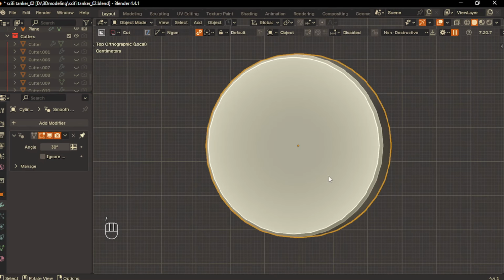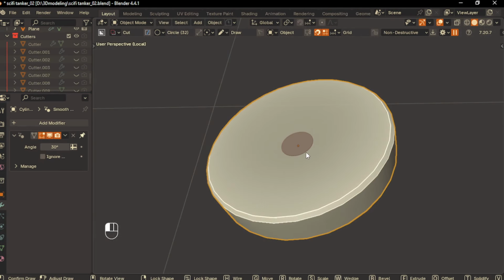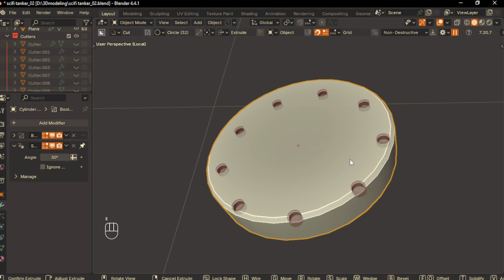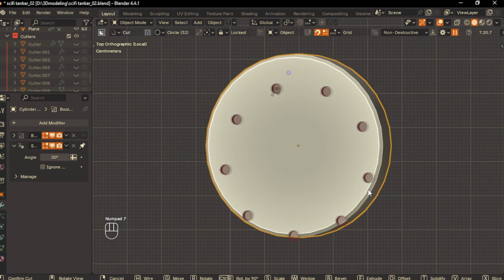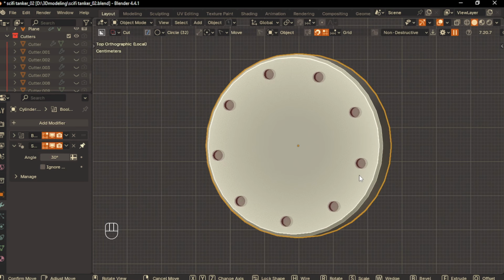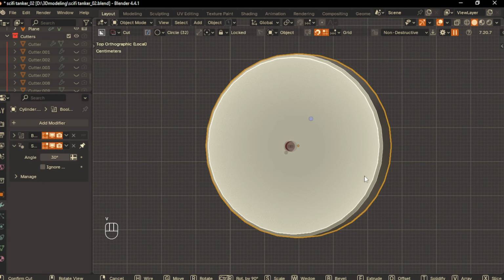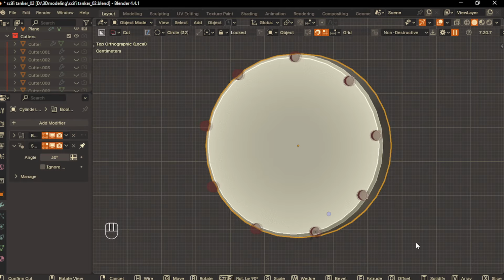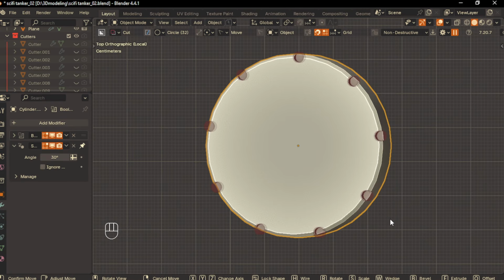Then enable box cutter. Now, let's perform a small circle cut here and press B twice to activate radial array and increase the count to form multiple teeth, then extrude the cut inward. It's a little bit off, so let's trace the operation and press G to move it. You can enable the array again and add a bit more separation between each circle for a better distribution. Once you're happy with the placement, adjust the position and make the cut.